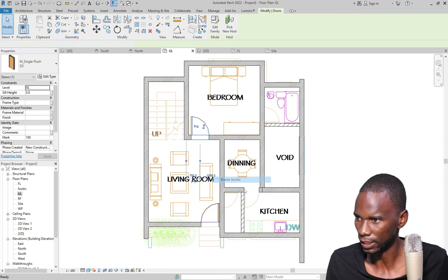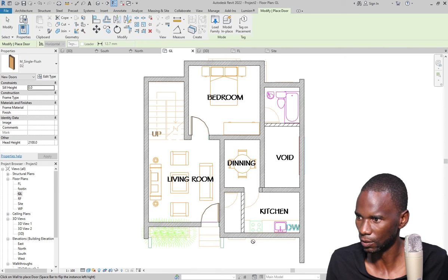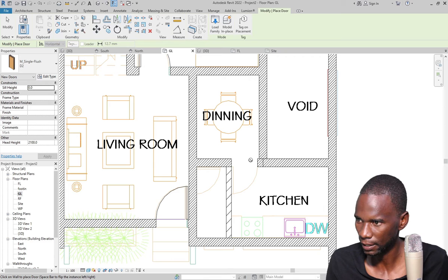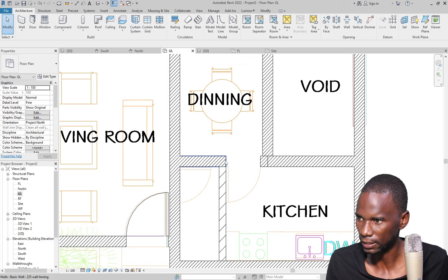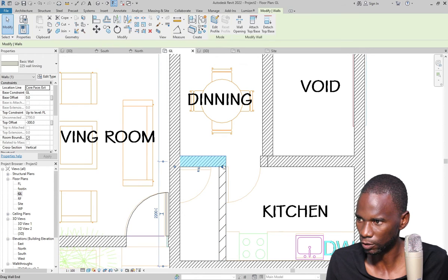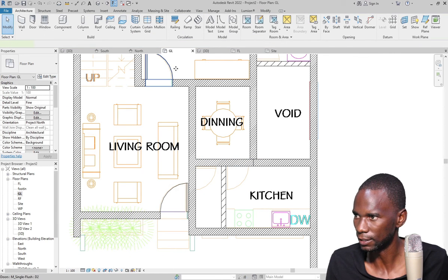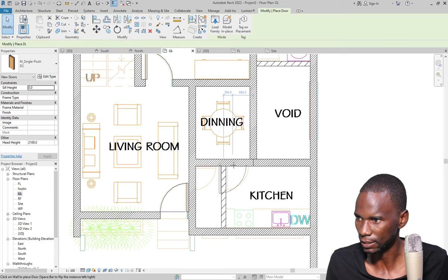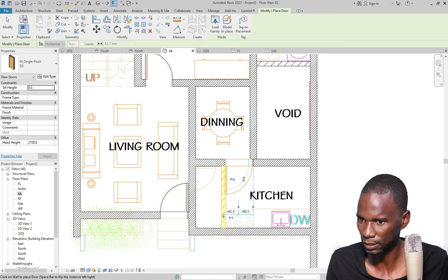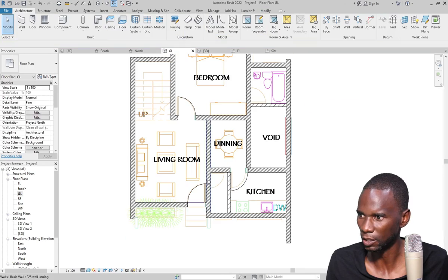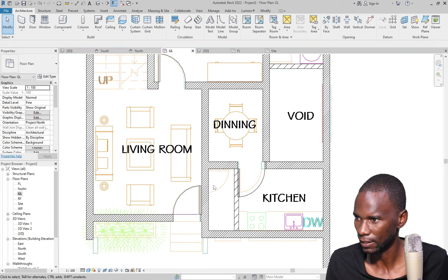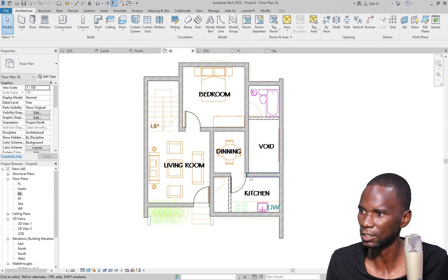Then I'll right click and create similar one. Do we have a door of the same type? Okay, maybe right here. Now you see that here I didn't close this gap. You have first of all to drag it, and I want to close it there. Then I can place this door, select one, right click, create similar, and I just want to have the door there, but it seems the space is not enough, but I'll try to place it there, modify. Okay, I can change the size because it's not fitting here, but let me not waste time on that one and go ahead and change the size. Okay, we have this one. I'll leave the others, maybe just that one.